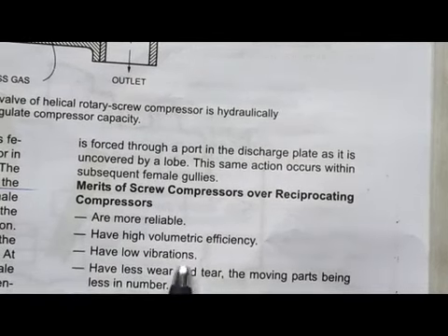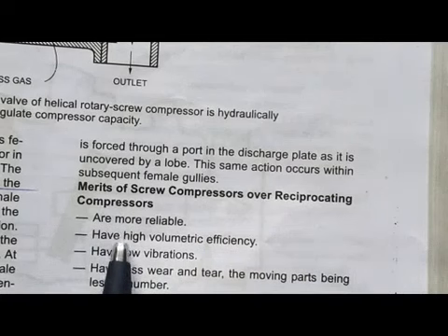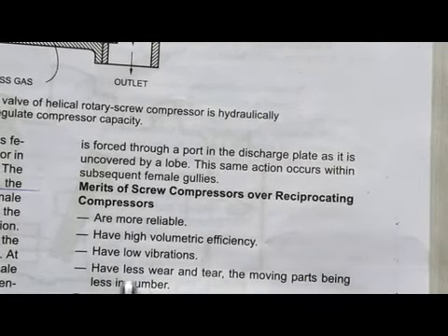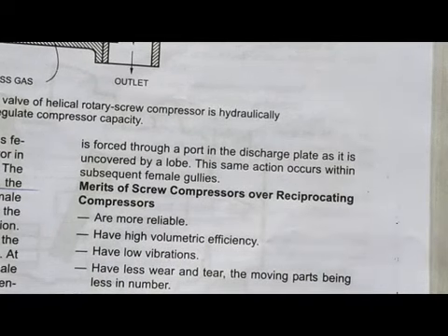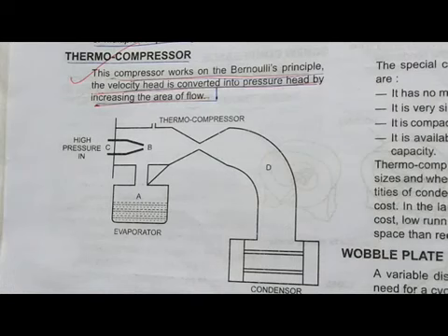The merits of the screw compressor over the reciprocating compressor are that it is more reliable, has high volumetric efficiency, low vibration, and less wear and tear of the moving parts, so it requires less maintenance as compared to the reciprocating compressor.